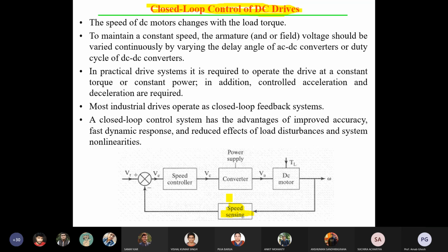Okay, then it is coming to whom? Then comes the threshold value, the reference voltage. That reference voltage is given in the truth table, the reference RPM. Here omega is in RPM, so here you are giving the voltage, and that voltage is equivalent to the RPM. Suppose 1500 RPM, some voltage is given by the data sheet. In the truth table it is mentioned 1400 RPM. Based on the set value, you give that value. That is called set point tracking. In control system terminology, it is called set point tracking.